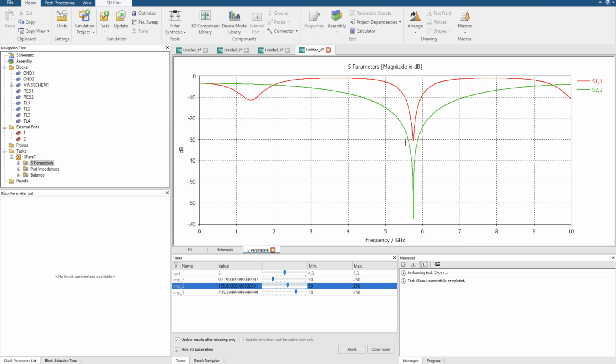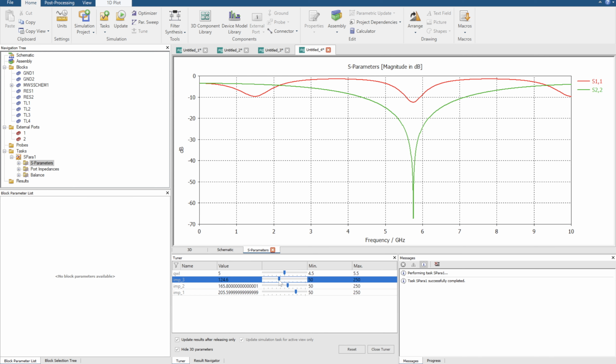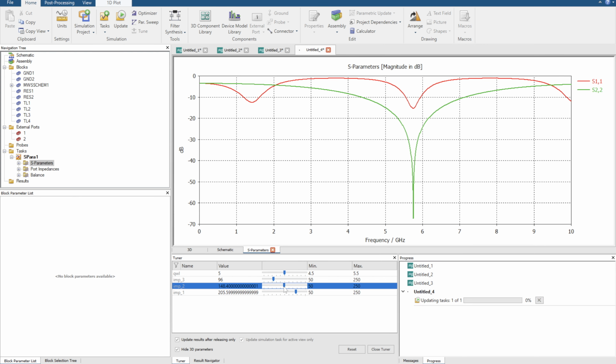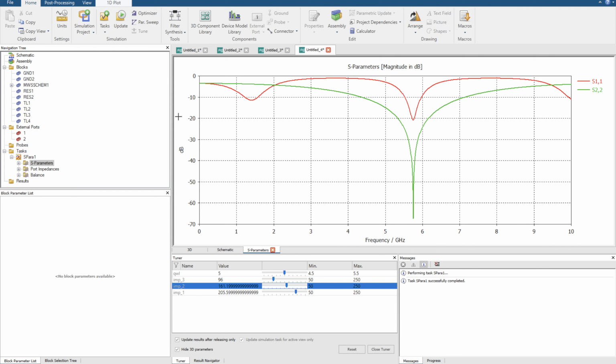So I'm just trying to get the red line as low as possible. Okay, we're not having too much luck. But even then, your goal for an impedance matching circuit, depending, -20 is very high performing, meaning only 1% of the power is being reflected. But you can see this perfect impedance match here is far better than what I'm attempting to tune, and so forth.